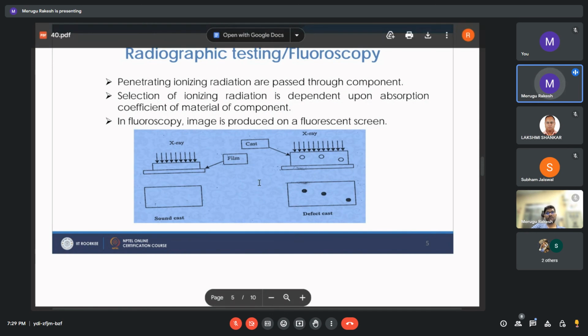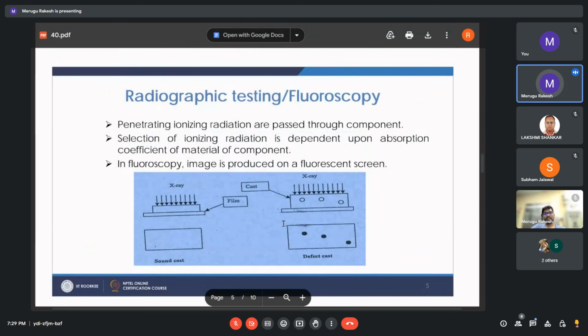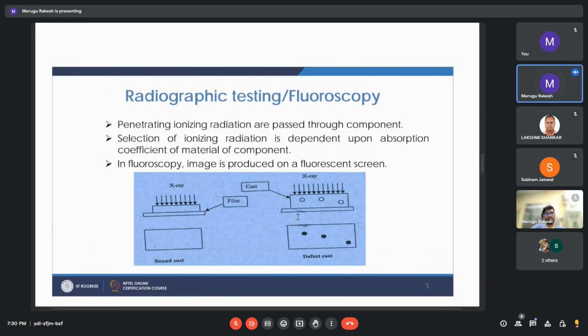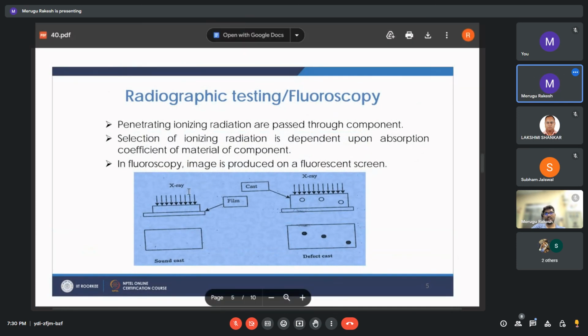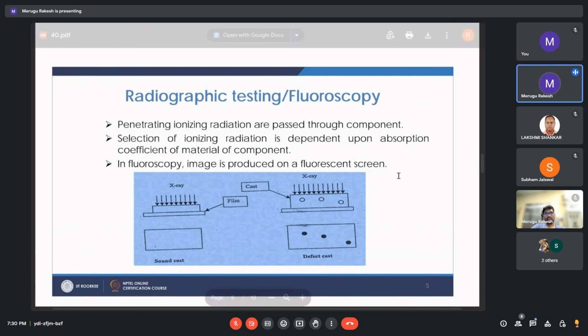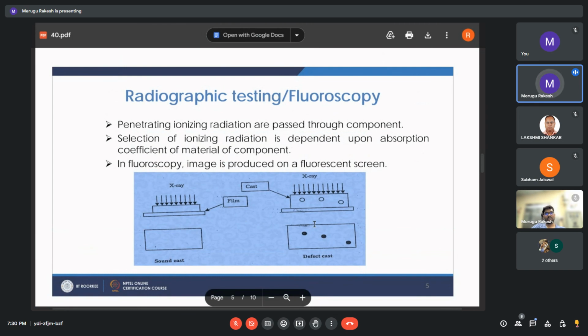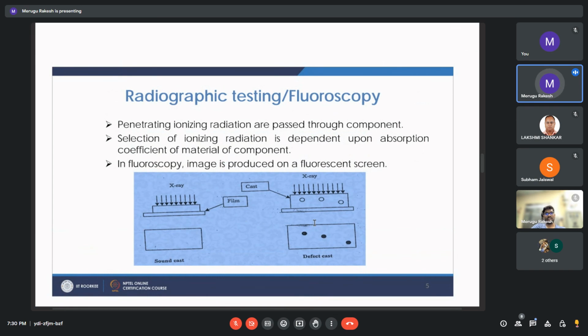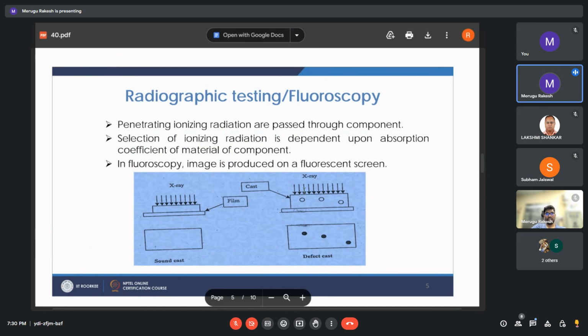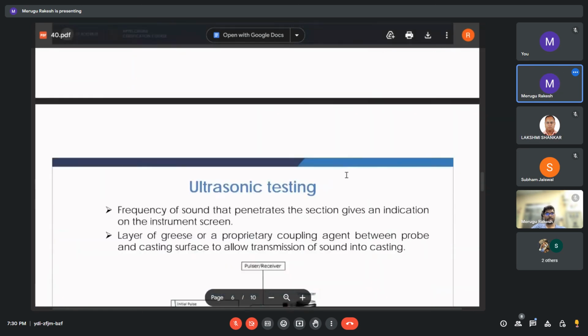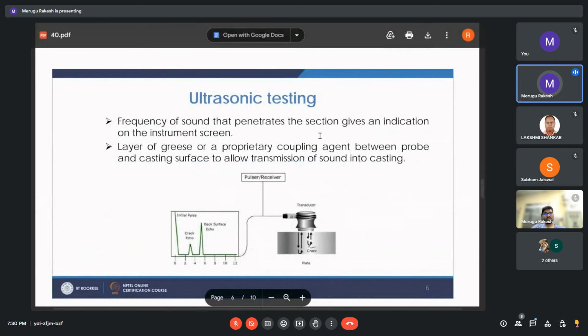Basically, we have one more technique in this radiography. We also have X-ray tomography, in which we can get a 3D scan. Using the same principle, X-rays, we just keep some setup stage such that it will rotate 360 degrees, so that we can get the complete 3D structure of an element, which is popularly used nowadays.